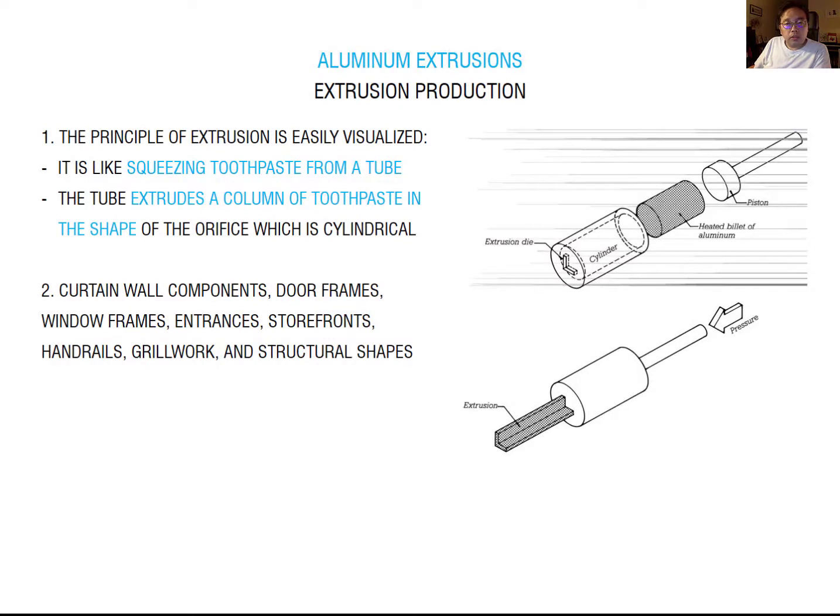So now we talk about aluminum extrusion for the window frame. The window frame mostly uses the aluminum extrusion fabrication process. Extrusion is defined as the process of shaping material by forcing it to flow through a shaped opening. You can see this is a simple diagram. This is an extrusion die. Depending on this shape, you can get some desired pattern. Simply, you use a heated aluminum block, and then this piston pushes in, like toothpaste, and depending on the pattern here, you get the desired shape.